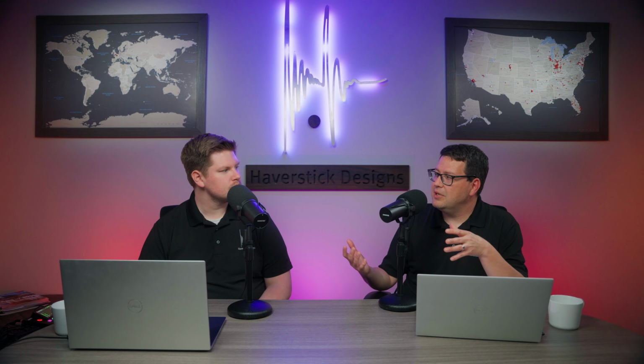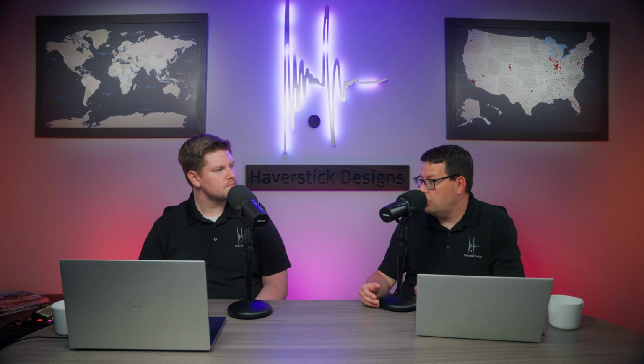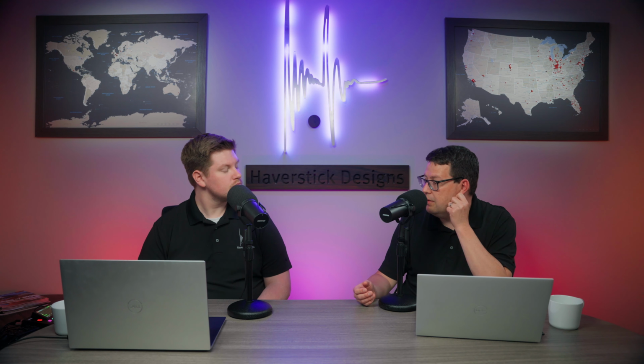The other thing is that reflection off of that wall helps reinforce the direct sound and can help speech intelligibility, especially for people in the back of the auditorium. So overabsorbing those sidewall reflections isn't great. And if we can diffuse it using diffusers or a hybrid product like perforated facing on top of the absorption, where it doesn't absorb as much high frequency energy and absorbs more low frequency energy, it can bring balance back to the room and help on all fronts when it comes to speech intelligibility and musical quality.